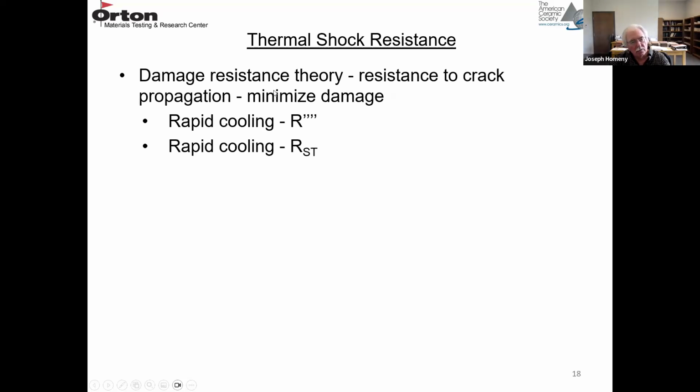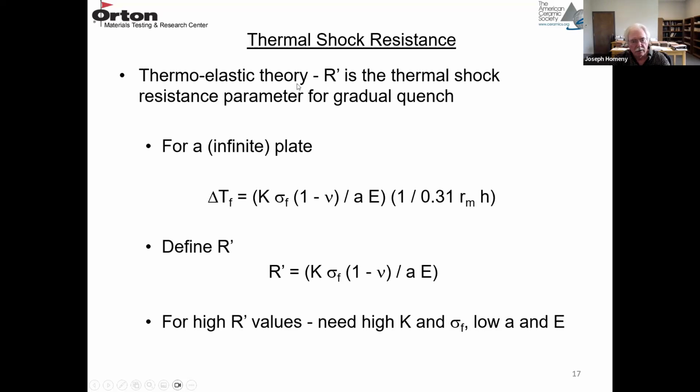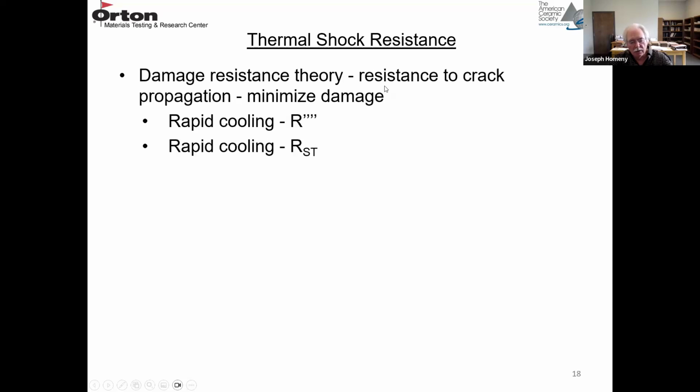The theory that's used for refractories is a damage resistance theory. And here you're resisting crack growth. In the thermoelastic theory, you're resisting crack initiation. Unfortunately, in the thermoelastic theory, when you initiate a crack, it's usually catastrophic. In the damage resistance theory, you allow cracks to initiate.